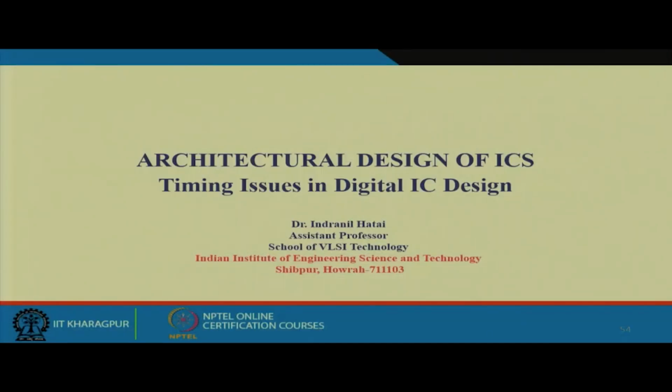So, we are discussing mainly the timing issues which we find in digital IC design. Till now we have discussed several problems which we have to consider to check the actual performance of the chip whenever it works in real time. So, we have to constrain our clock with all the aspects of the original behavior of the clock, so that we can get the actual performance of the circuit while we are doing the simulation.